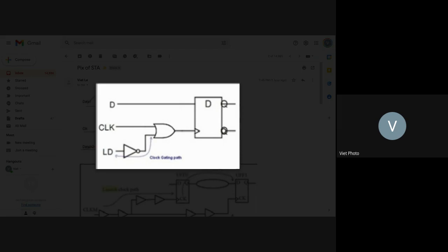It doesn't work on purpose, because where they block it here, it doesn't need to work. That's different from a case where you have a clock going here but, because of some stuck-at fault or failure, it doesn't work. This one is a flop operating on purpose, so there's no switching and no power. That's how they reduce the power.